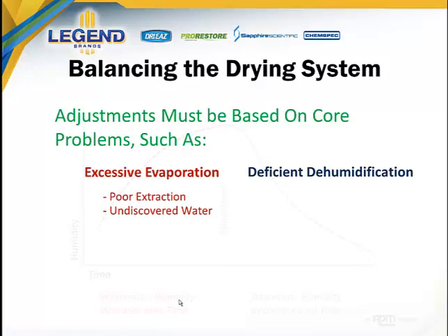The appropriate solution is to address the excess water through proper extraction, proper mitigation, and then recalculating for the size of dehumidification needed based on the new discovery for the number of wet areas, rooms, and spaces, and the scope of damp.